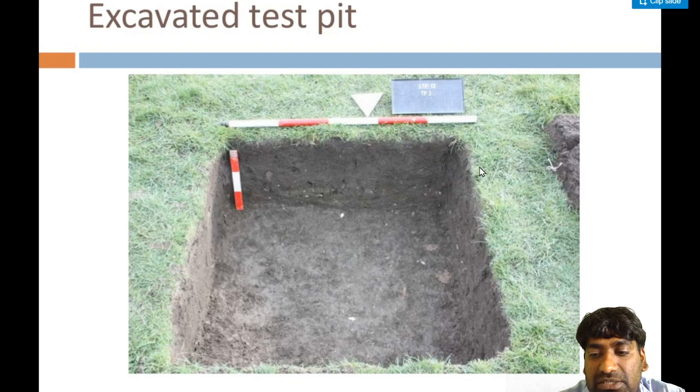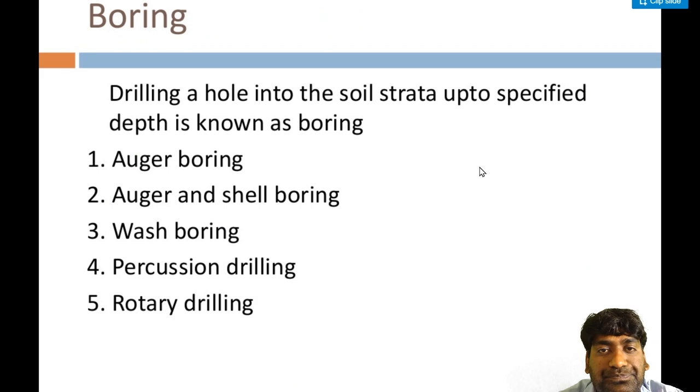It is very necessary to go through these test pits if you are going for any type of construction, any type of infrastructural development like buildings, hospitals, hotels, bridges, flyovers, tunnels, any kind of construction. You must know about the subsoil condition of that site: what type of soil is at what level. Which type of soil is present there, then you decide the foundation, and at which level the water table is available.